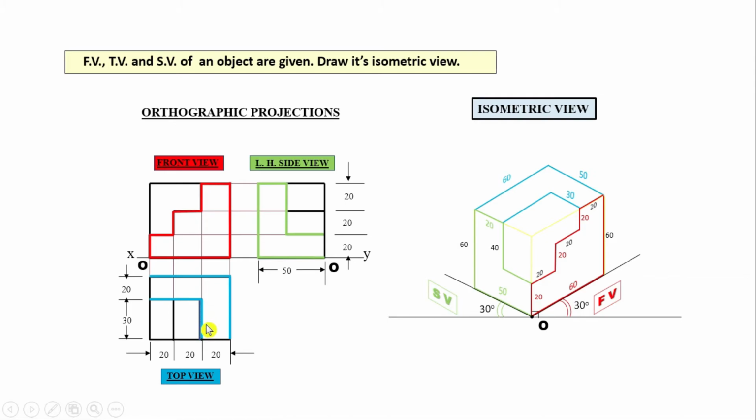A different dark color is provided. That will start from here. It is of 30 mm length. Now we move to this point. This line is visible easily, that is 30 mm length. All these lines are parallel to this 50 mm line, or you can say this yellow line. Now below this line again one line will be there, again of 30 mm length. So here you go, 30 mm length. So this should be visible in the top view.